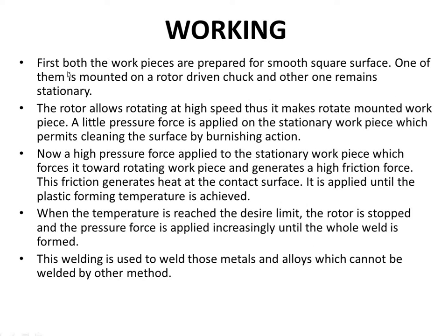Let's see the working. First, both the workpieces are prepared with a smooth square surface. One of them is mounted on a rotor driven chuck and the other one remains stationary. The rotor rotates at high speed, thus rotating the mounted workpiece. A little pressure force is applied on the stationary workpiece, which permits cleaning the surface by burnishing action.